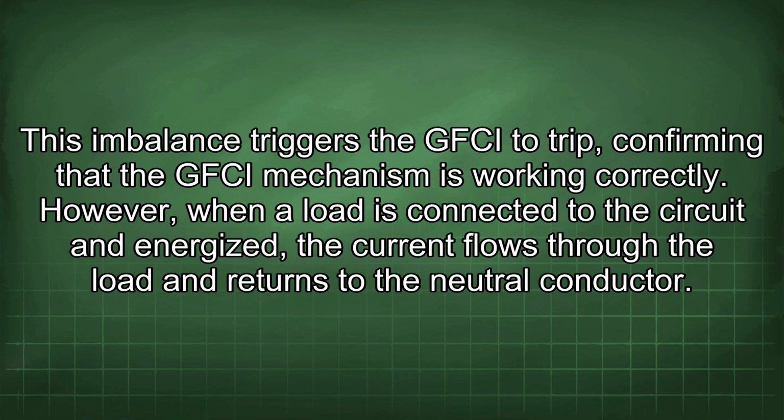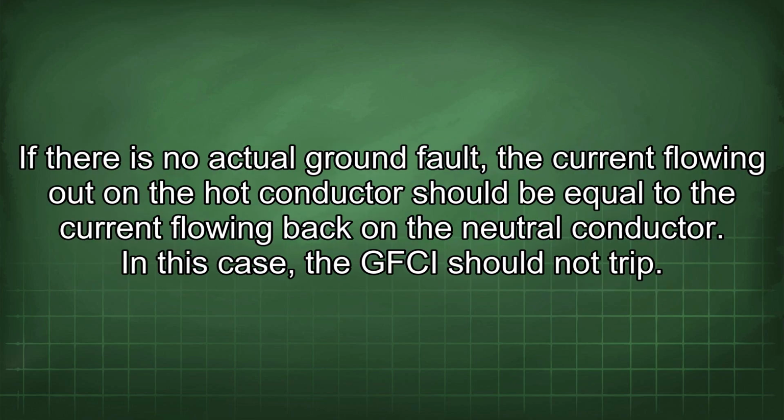However, while a load is connected to the circuit and energized, the current flows through the load and returns to the neutral conductor. If there is no actual ground fault, the current flowing out on the hot conductor should be equal to the current flowing back on the neutral conductor. In this case, the GFCI should not trip.